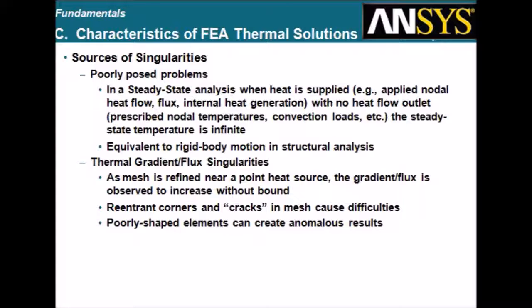In a steady-state analysis, when heat is supplied, e.g., applied nodal heat flow, flux, internal heat generation, with no heat flow outlet, prescribed nodal temperatures, convection loads, etc., the steady-state temperature is infinite. Equivalent to rigid body motion in structural analysis.